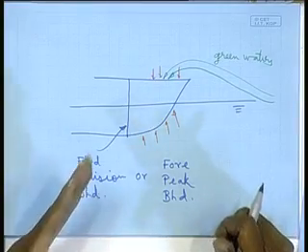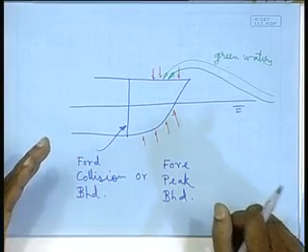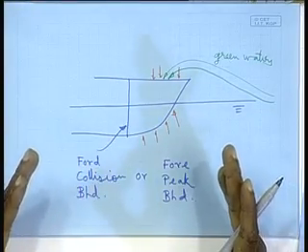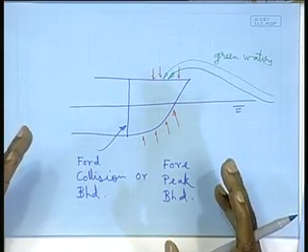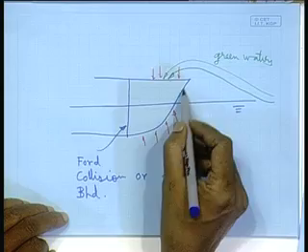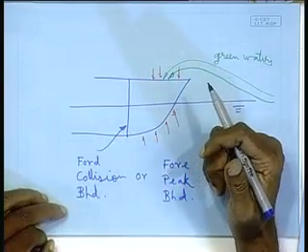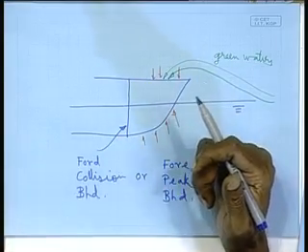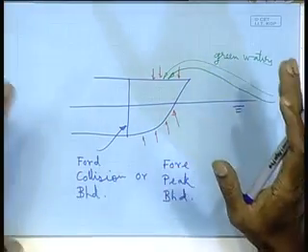Right. What is the very logic of this? Why this name, forward collision bulkhead? So, the idea is, in the event of some situation where the ship may hit head on, this part should be able to absorb the entire impact load. You can well imagine the momentum of the vessel by virtue of its size.